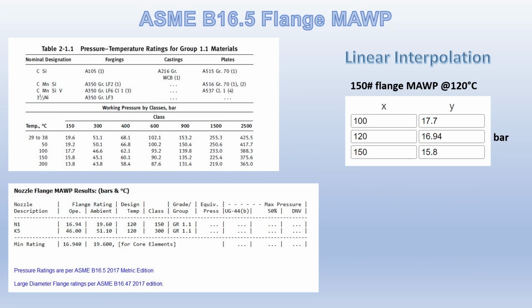To make sure, we will double-check it with the relevant group table of ASME B16.5. This double-checking section is added for good engineering practice. If we don't do this habit, young engineers will always depend on software auto-generated values and will forget where these reference values came from.